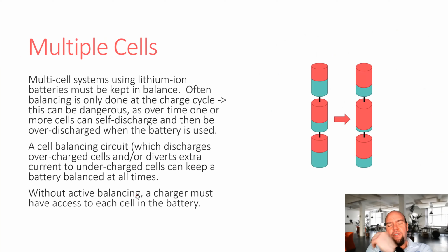Multiple cells. So far we've glossed over this notion that the standard lithium technology batteries are anywhere between 3.3 and 4.5 volts per cell. A lithium ion has an ionization energy of like 5 volts or something, but for practical reasons, the most you can usually extract is like 4.5 volts or so. Again, I'm not a chemist, but typically with these lithium-based batteries, you're going to get 3 to 4.5 volts per cell.